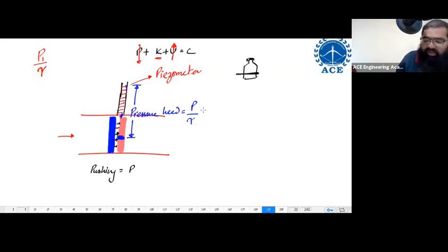If you have a doubt about how we get this pressure head, suppose between point 1 and point 2 I'm applying the Bernoulli equation. So P1 by gamma plus V1 square by 2g plus Z1 is equal to P2 by gamma plus V2 square by 2g plus Z2.